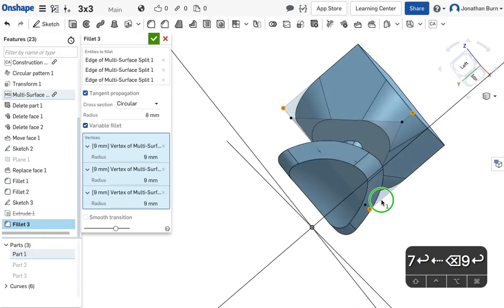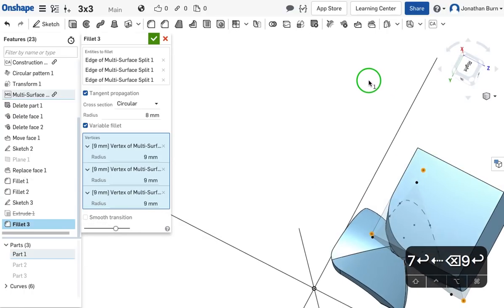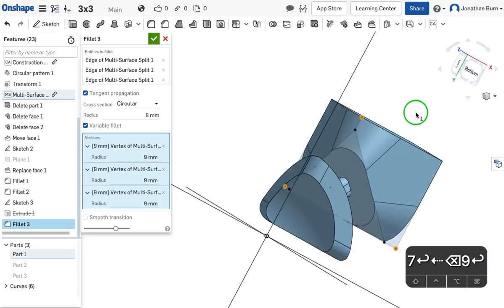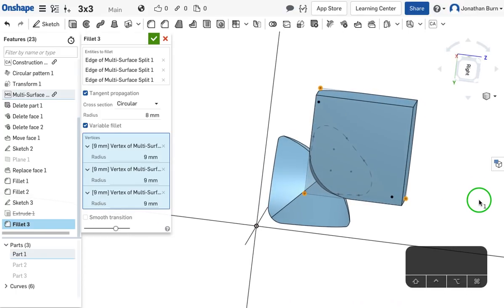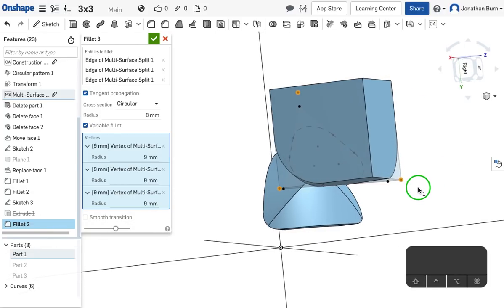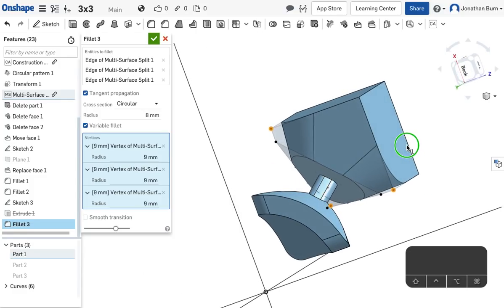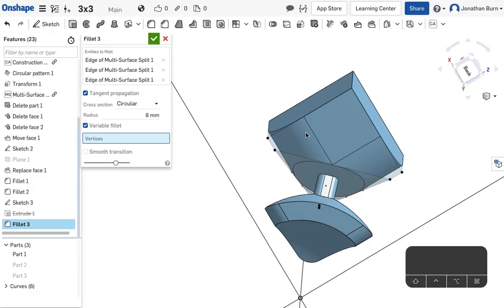What that does is it basically goes from the value of that fillet to the value of that fillet. So when this corner piece is on top of the other piece, you want this fillet to go from smaller to larger, because when the pieces are misaligned and you actually need the fillet, then you want this line right here to line up with the piece, because that's the line where the tapering ends. If you don't have this, it's just a straight line, because this fillet area over here doesn't even matter.